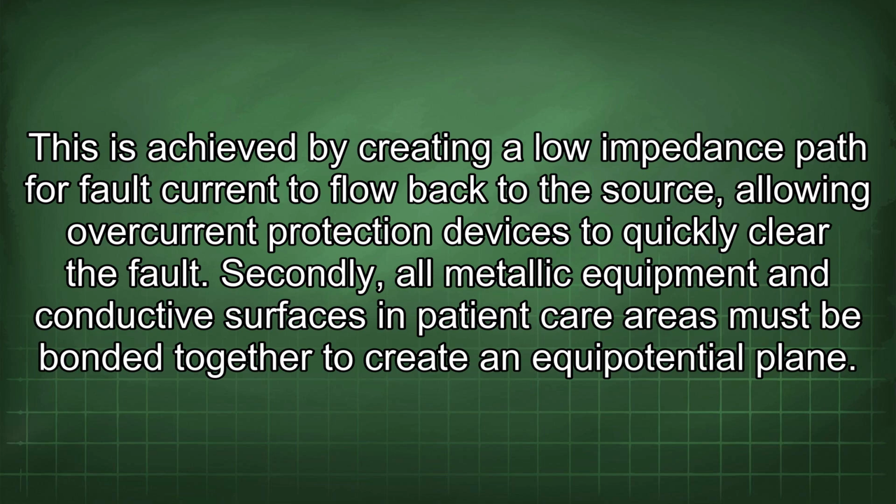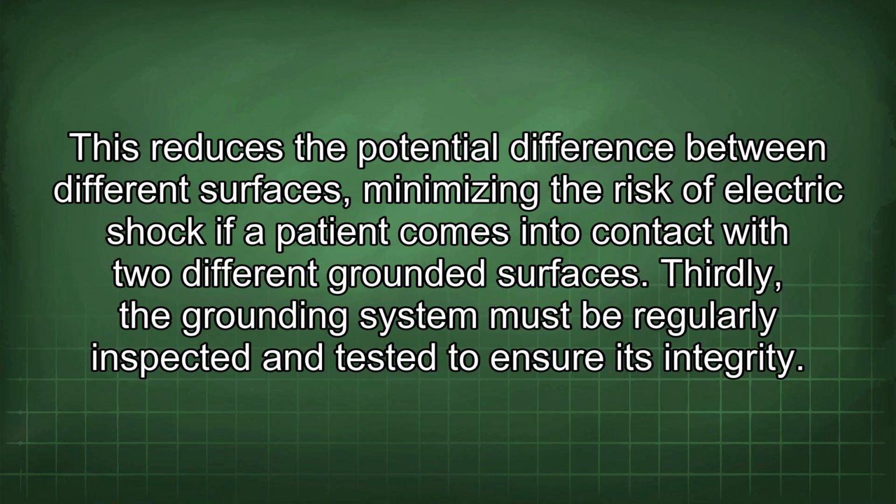Secondly, all metallic equipment and conductive surfaces in patient care areas must be bonded together to create an equipotential plane. This reduces the potential difference between different surfaces, minimizing the risk of electric shock if a patient comes into contact with two different grounded surfaces.